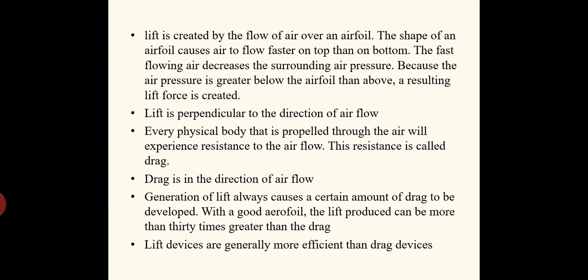Generation of lift always causes a certain amount of drag to be developed. With a good airfoil, the lift produced can be more than 30 times greater than the drag. That is very important. With a well designed airfoil, the lift force can be more than 30 times that of the drag. So of course the energy that we can harvest by using lift technology will be much higher than that we can expect from the drag.